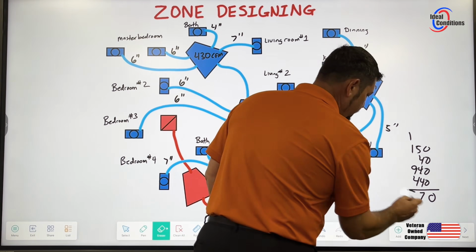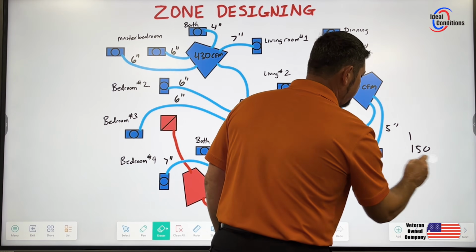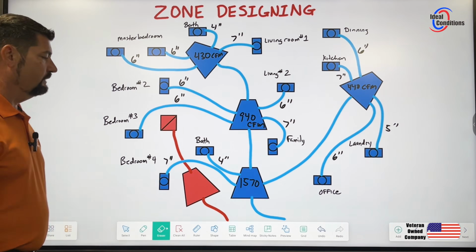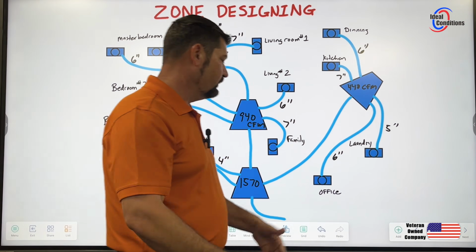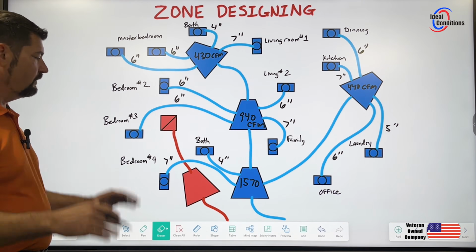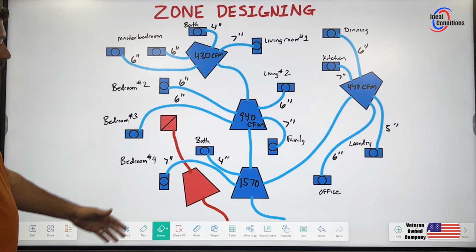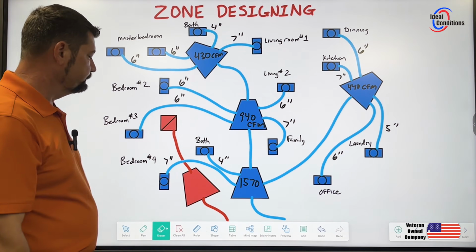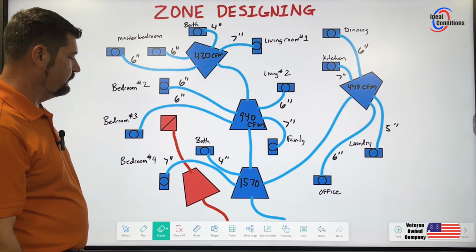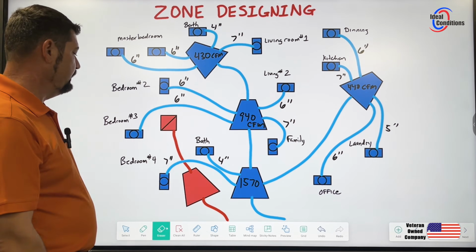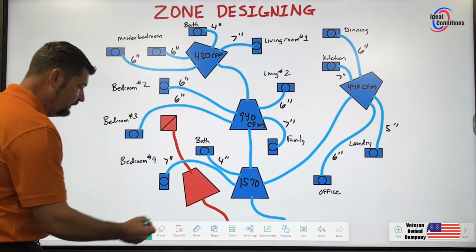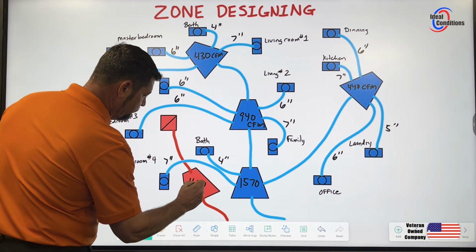So we're just going to make this simple and say, hey, we had a 1,600 CFM air handler. It was 4 tons, and it's right within its range there. Now, we'll get into other videos, like I said, where we do airflow and we talk about oversized and undersized, and I'll give millions of examples if we have to, until we all feel like we just understand it. So if I have 1,500 CFMs coming to it, then basically, 1,570 CFMs leaving the machine, I have to have about 1,600 CFMs returning. So we're just going to say that this is 1,600 CFMs.